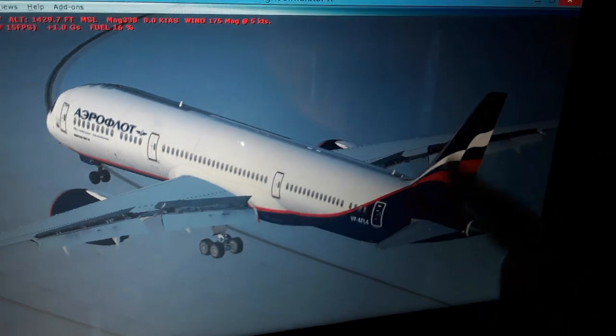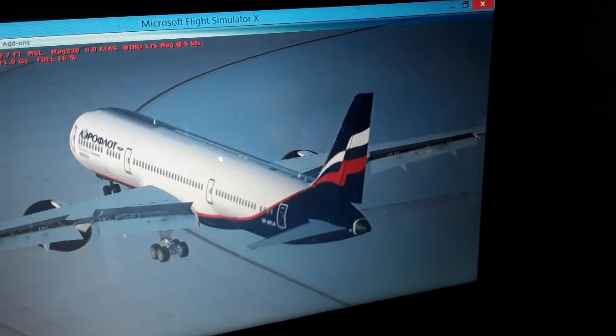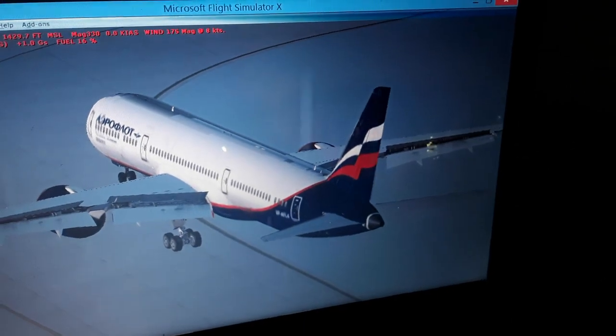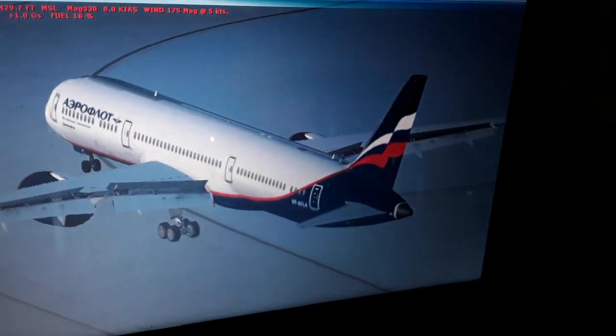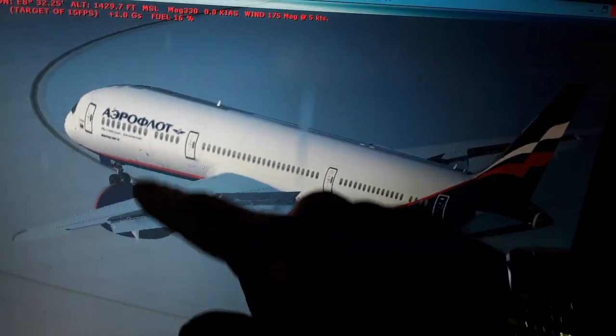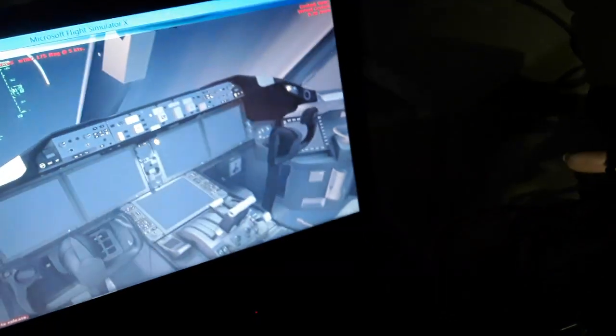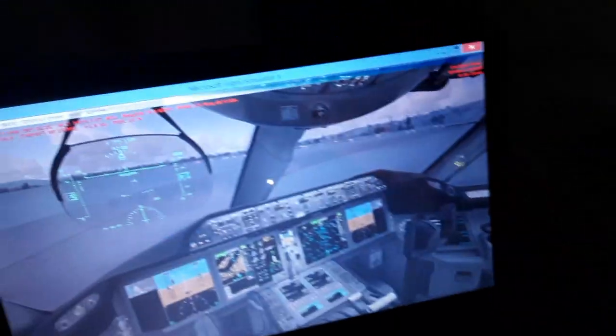So above 144 kilometers an hour we have the rudder only to control the aircraft until we take off, then we are flying. Then when we land we have the inverse. As we land, first we have the rudder, then as we slow down below 80 knots the forward nose wheel becomes activated from the computer.